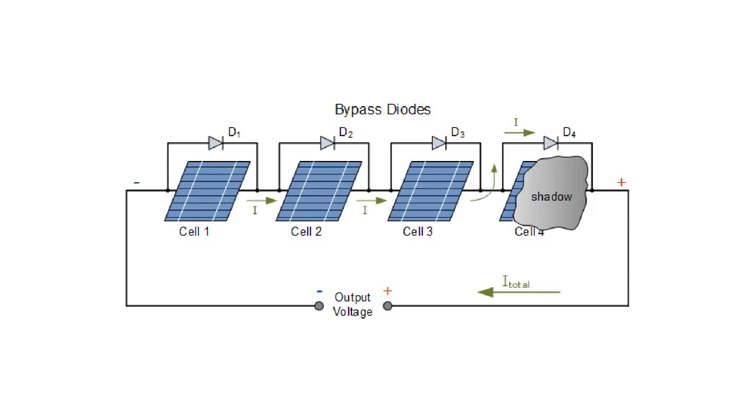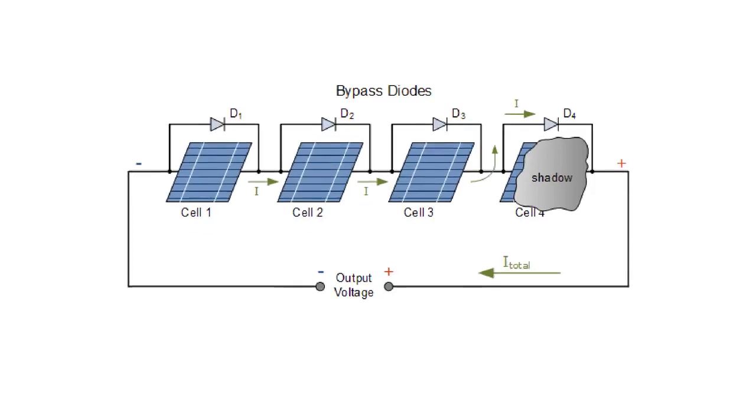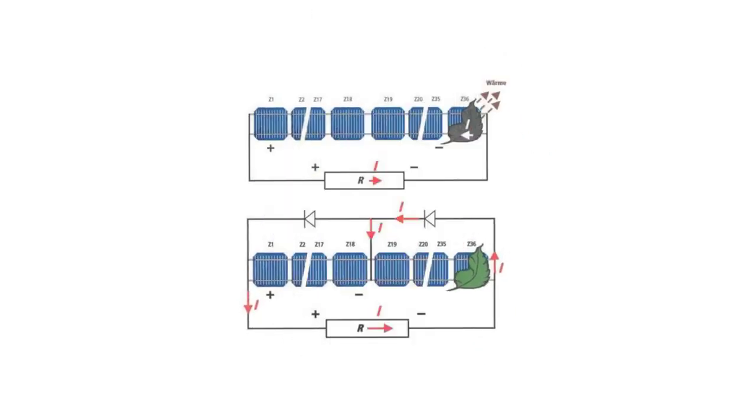Similarly, a system can also be designed with a bypass diode instead of microinverters if shading is a concern. A bypass diode is a cheaper but a less efficient solution for the shading problem. Please note that it is not always possible to place panels on the field. Obstacles are always around that can include buildings, trees, electricity or communication poles, etc.